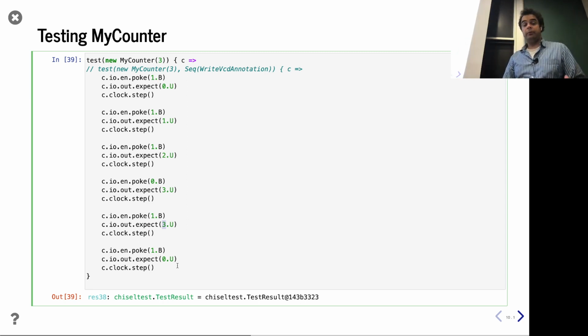As the course goes on, we're going to get better and better at using Scala to actually generate these test cases. Rather than manually imagining every single cycle, which as you can imagine is very error prone and very brittle, what you want is some Scala that programmatically, functionally does the thing you want to be doing, and use that Scala to generate the test cases. We'll cover that more in future lectures. But for today, it's very verbose, copy-paste kind of twiddling stuff.